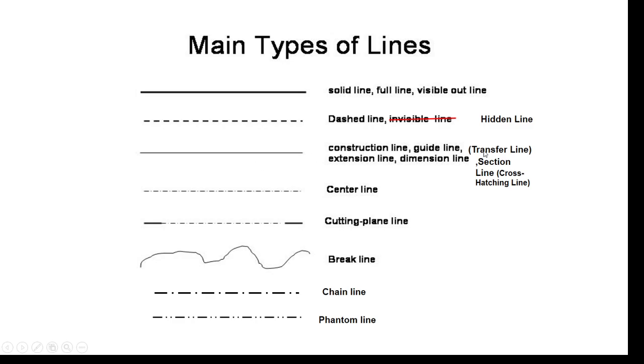And we already talked about transfer lines. Drawing thin continuous lines, we can transfer abscissa, ordinate or altitude values from one picture plane to the other picture plane, from one part of the drawing paper to the other part, for having the views consistent with each other.